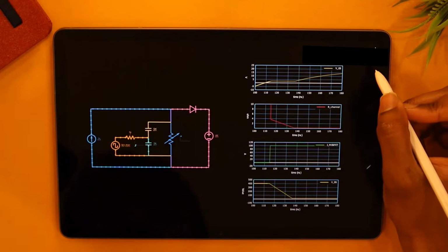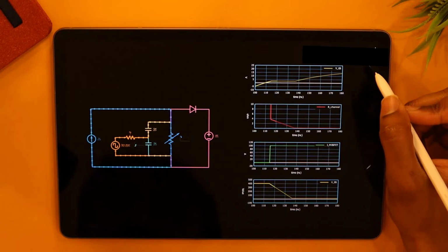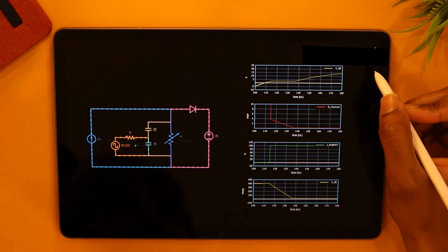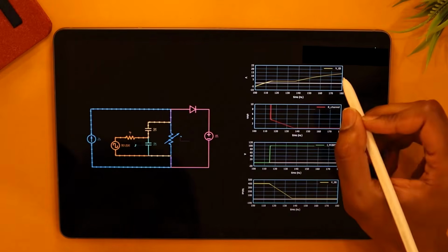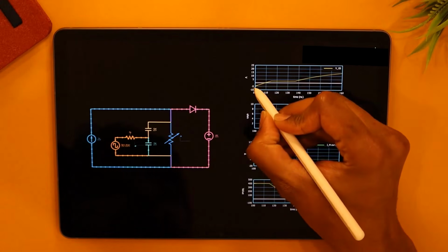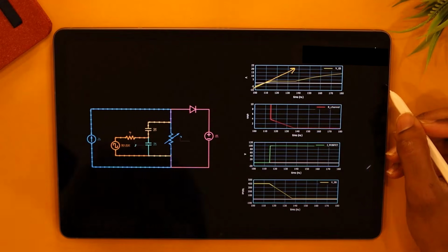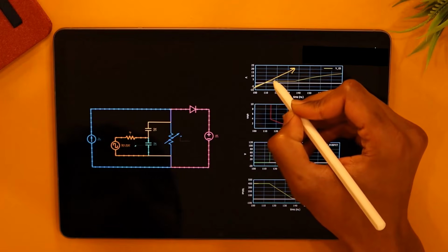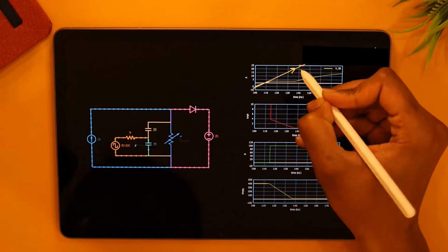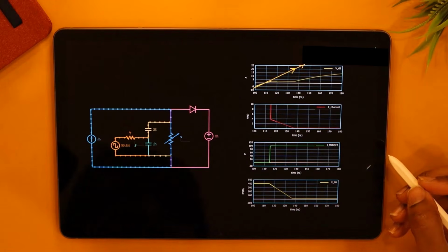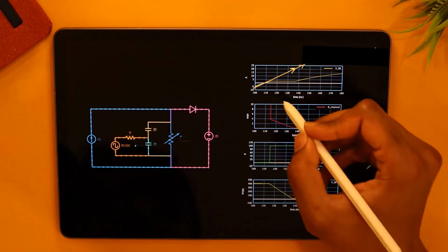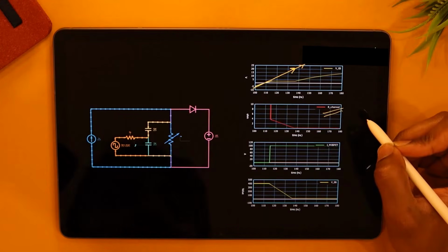So to understand why the plateau occurs, there's one easy way. Let's make an assumption that the VGS kept increasing instead. Let's say that there's no plateau. What would happen? At this moment, look at this, the gate voltage, I've just allowed it to increase. What would happen theoretically? If this happens, look at the resistance waveform.